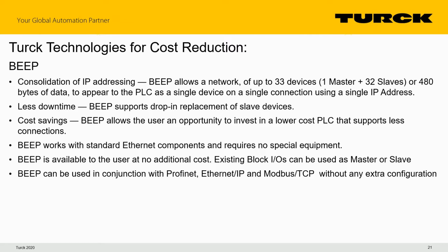So you can do that a number of ways. I mean, most of the protocols can be either selected to use multicast or unicast at the PLC. You could use a managed switch to narrow down that focus of multicast versus unicast. Our block will respond as it is requested to. So I don't believe we really have much of a setting in the block to deal with multicast or unicast.